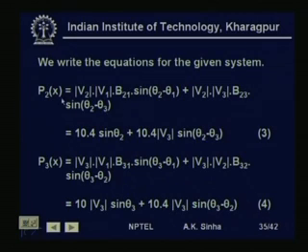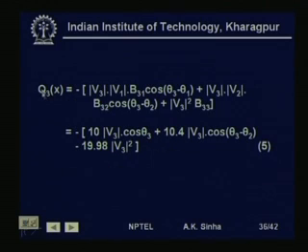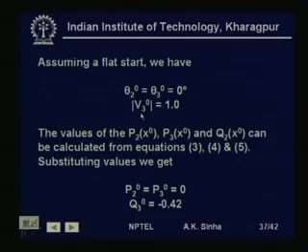Now, we can calculate the value of injection at bus 2 and bus 3 using the values of V and theta, or delta, that is the phase angle, using the expressions for real power injection at bus 2 and 3, and similarly the reactive power injection at bus 3. So, once we assume a starting value, normally, as we said earlier, we assume a flat start.